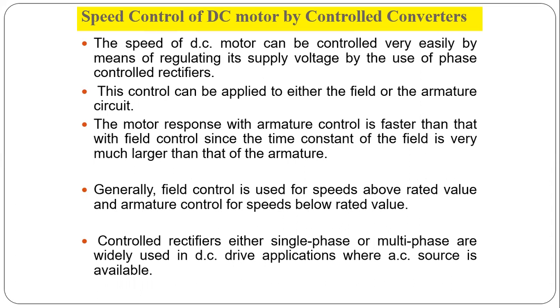The motor response with armature control is faster than with field control, since the time constant of the field is much larger than that of the armature.